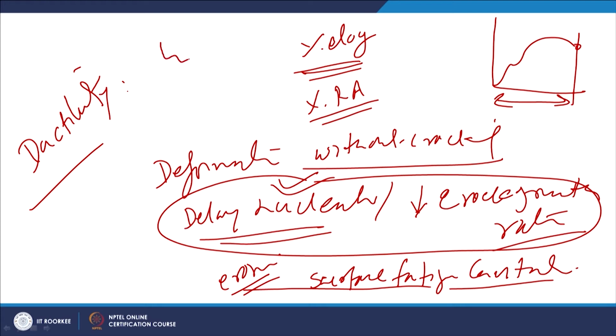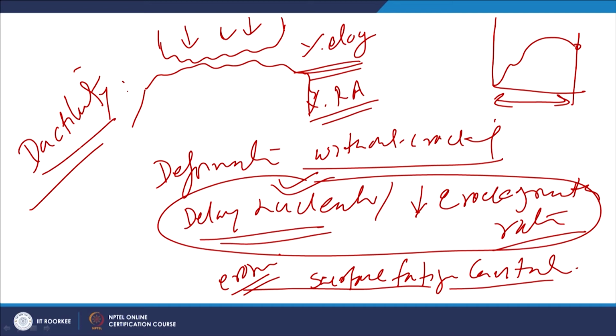At the same time, if the material has peaks and valleys at the surfaces, because of the high ductility of the metal, these peaks and valleys will collapse under the actual stress conditions during the service, and collapse of these peaks and valleys at the surface due to the ductility will lead to closer intimacy between the metals from the two sides without development of cracks. If the metal has very limited ductility, then it will not deform, rather it will break or get fractured, and the material will be removed in the form of fine pieces.